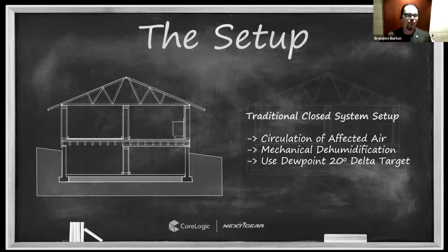You're dealing with a lot more materials that are dense and difficult in releasing moisture. You're also lacking the ability to really establish any ventilation with the outdoor air. And generally with substructures, I really try to leverage outdoor air ventilation whenever possible for lots of reasons, and we'll get into those. But in a true below grade basement, that can be quite difficult. So in many cases with a true below grade basement, your equipment setup is going to look very, very typical to your normal installation in an above grade structure.